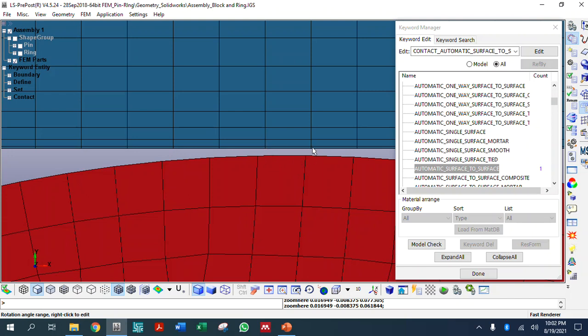So let's say if the element here is already deleted due to wear, it's going to find the neighboring contact, which is the next one, maybe this element. But because we select the part pin as the part object, it cannot do it.